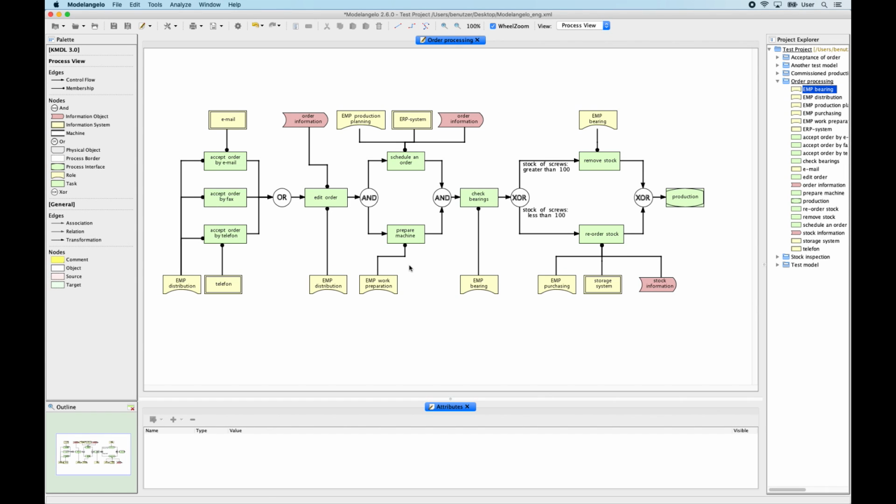You can also add physical objects to your process model. Physical objects can, for example, be samples, materials, or tools. They are physically present but have no information processing. To add a physical object to your process model, select the symbol in the left menu bar and pull it to the desired position while holding down the mouse button. To label, double-click on the shape and specify a name.